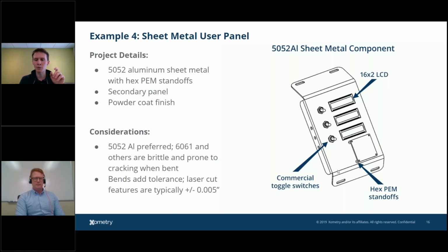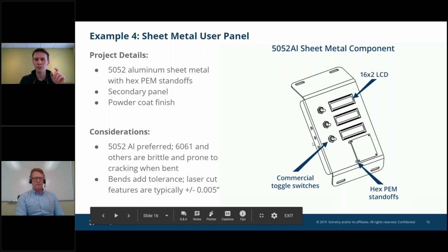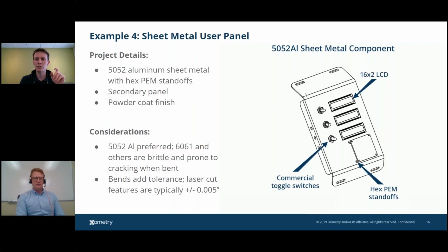We're showing that slots are being used on these features, and essentially, once you move out to bends, do add some wiggle to tolerance. So just understand when you're tolerancing for sheet metal that feature to feature is one process, right? I'm laser cutting. Edge to feature is a different process because I may be blanking in a different way here, and then bend to feature there again has its own tolerances. So there's little nuances to that.